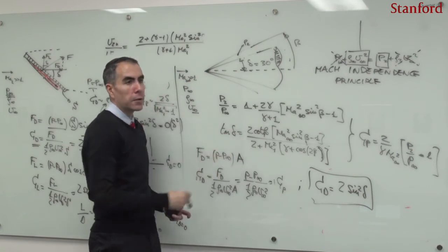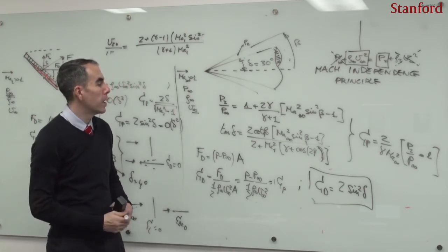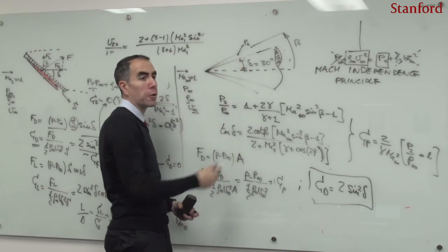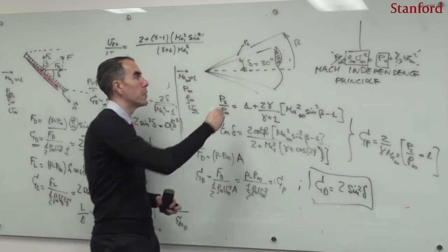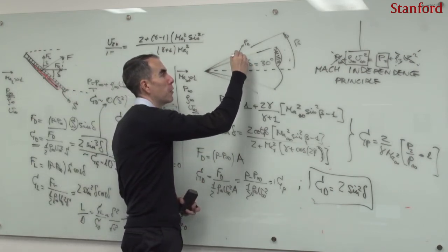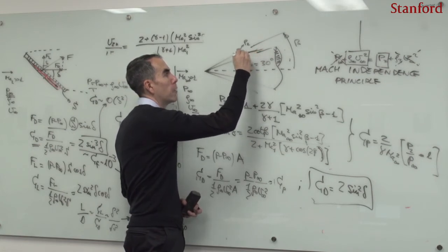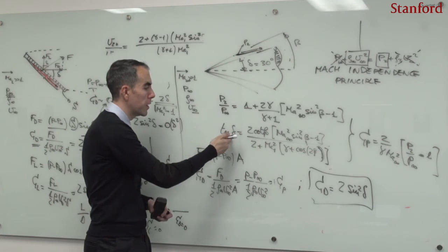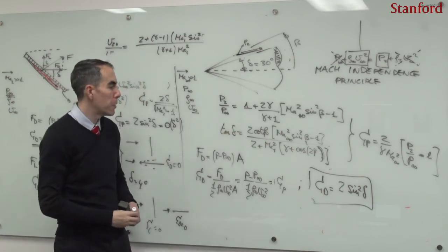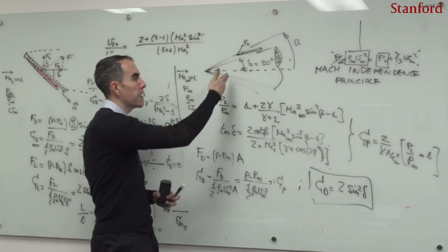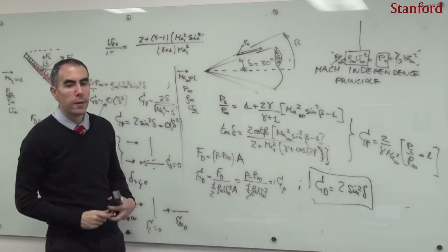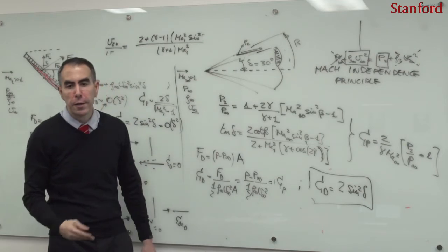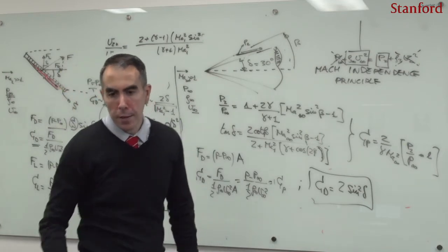this delta actually is kind of a useless angle, because this will be the streamline deflection angle just downstream of the shock. But that wouldn't be the streamline deflection angle of the streamlines all along the shock layer. So this streamline deflection angle actually varies with distance for the problem of a cone. So this problem here needs to be solved numerically, and we will learn how to solve it. There is a theory called the Taylor-Maccoll theory, whose results you can see in the next chart.